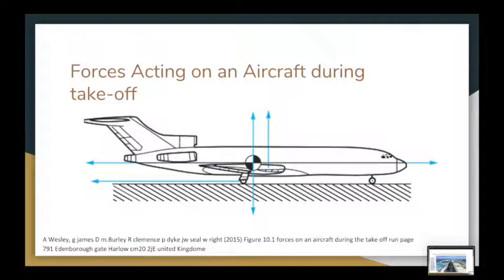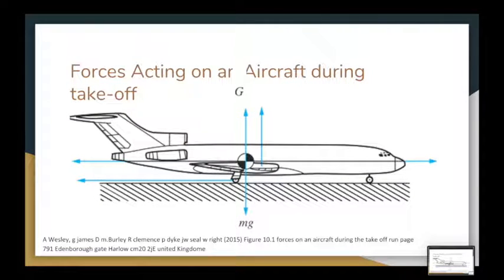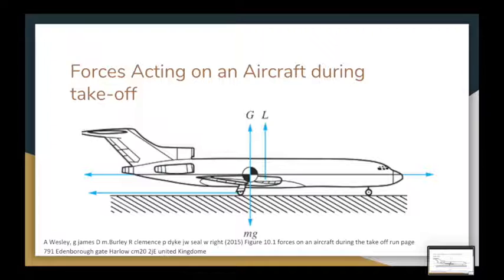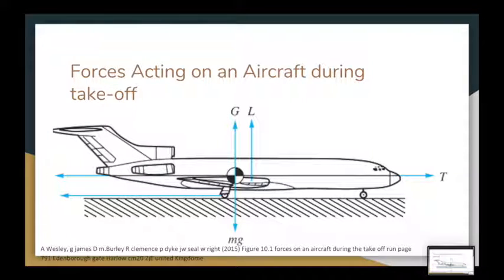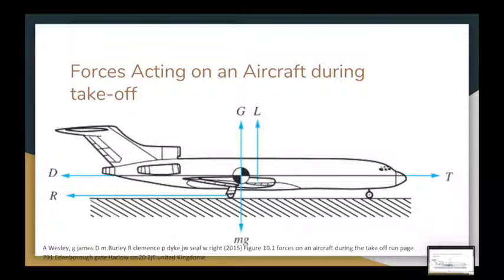To calculate a safe takeoff run, engineers had to create a precise model representing a takeoff of an aircraft. This model combines all components leading to an enabling flight. Force relations shared between the aircraft and its surroundings were gathered: mass of aircraft reacting with gravity, reaction force with contact point to ground, aerodynamic lift, thrust force from engine, aerodynamic drag inhibiting thrust force to a degree, and resistance with ground contact.